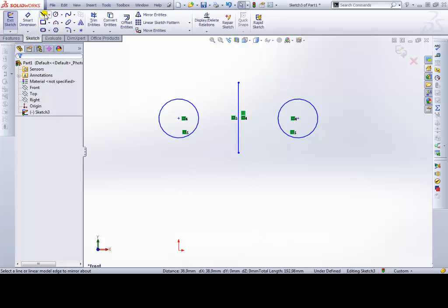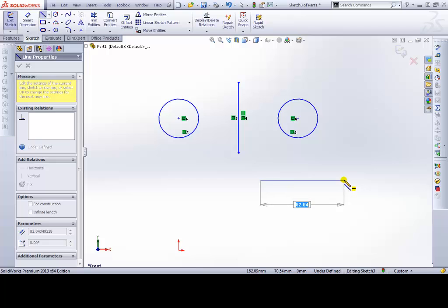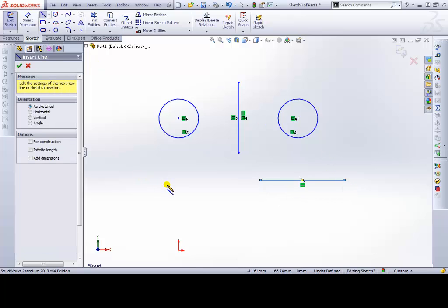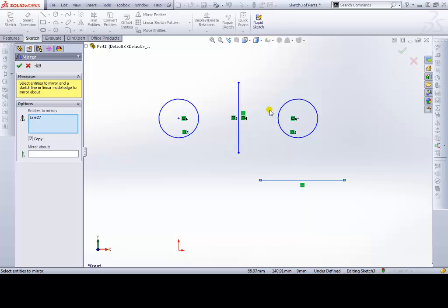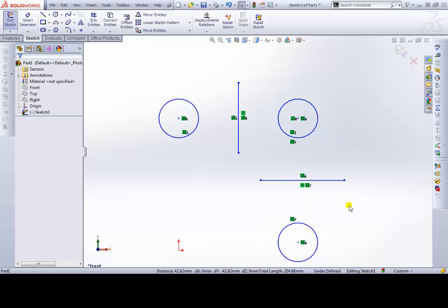this line. Let's go ahead and create one more line. I'll go ahead and accept that, and I will mirror the circle one more time. So I choose the circle to mirror, and then I place the line. Also notice right now I still had the line highlighted, so I have to come in here and delete the line in case you may pick up some extra objects that you don't want to actually mirror. Now I need to choose what I want to mirror about. I'll select the line, and again it's mirrored down across the line. I'll go ahead and accept that.